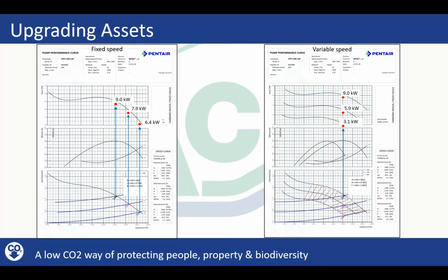Now, what you can see is as the head difference decreases, the pump pumps a larger volume of water when it's fixed speed. And you can see as well, the energy usage drops off. So a lot of people think, well, the energy usage is less and my volume of water being pumped is increased. So what's the big problem? Like, surely that's getting quite efficient. But it's not the whole picture.